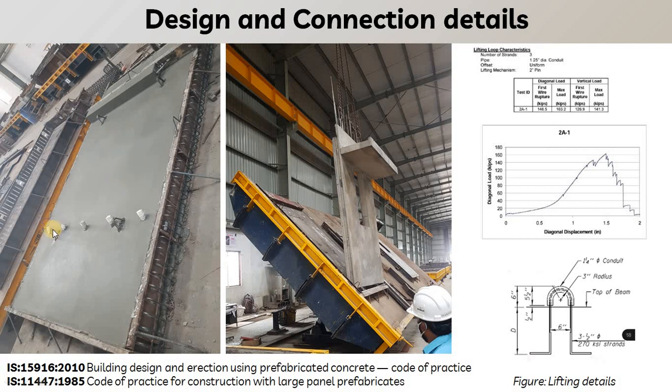And then here you can see horizontal lifting hooks are provided. So here the four lifting hooks are there, and here you can see this is the nib on which this hollow core slab will be resting. In our hollow core slab video, we have already discussed what the nib is, why it is required, and the purpose of the nib, which is a very important requirement to rest the hollow core slab.